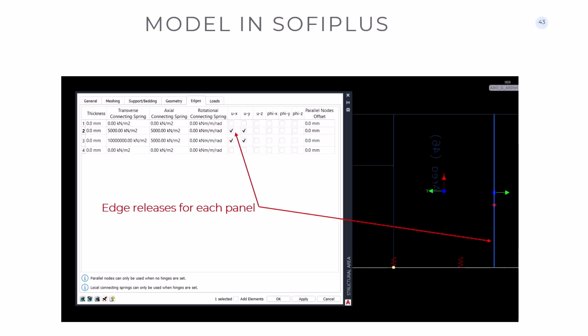And this slip seems a stupid thing, but it really completely changes the way the forces are distributed along the element. I will show you a picture and you will understand it. So in the case of SOFiSTiK, the advantage is that we have these edges and we can define what we want to disconnect. Actually, I think it's well done in the sense that when you define the edge, you get another axis, and these data are referring to this axis.